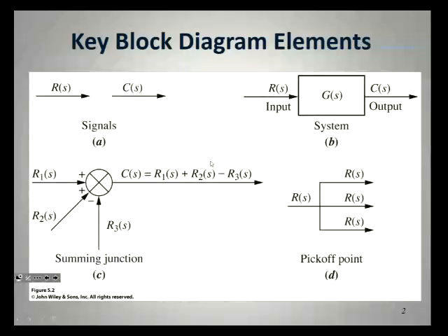But there's some main elements to a block diagram, which you've mostly seen already. You've got your reference input, which is always R. These are in the Laplace domain, obviously, as well. That's why you've got bracket sets here. You've got control output, so that's your main signals. You've got signals that do flow through the diagram as well, like E of S, which normally stands for the error that comes out of the error detector. That one's not, though. That one's actually a summing point. But if it's an error detector, you'd have an E of S here.